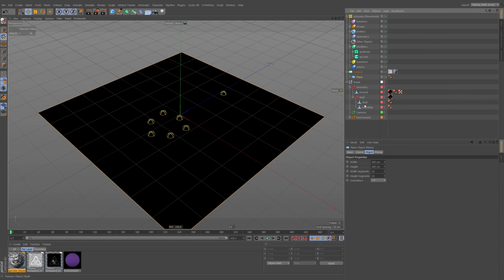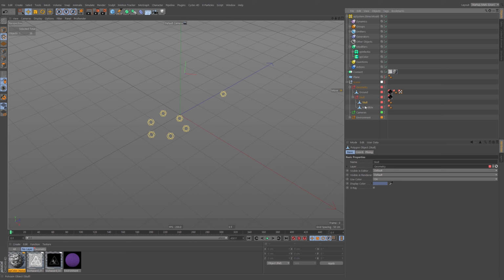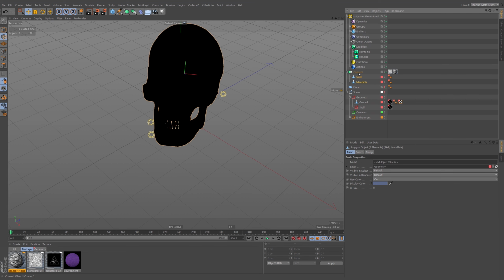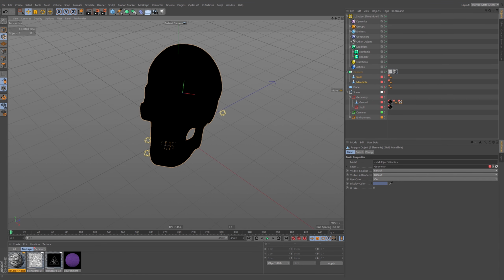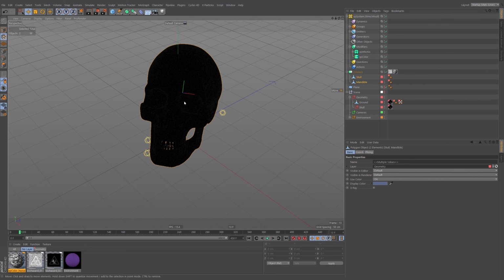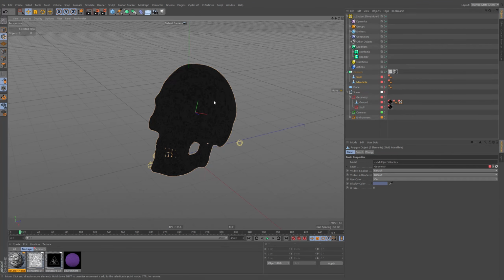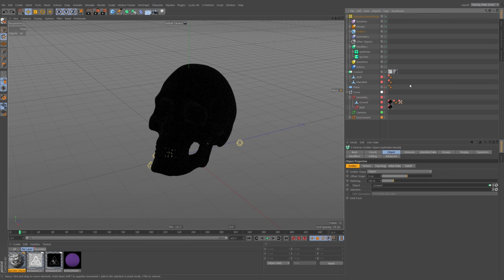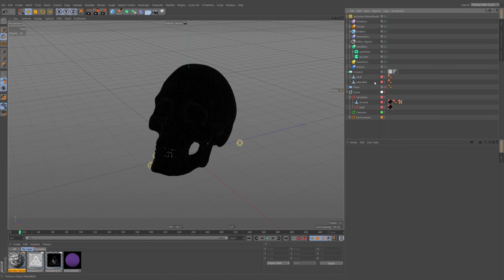Let's grab our skull and mandible. I just wanted to demonstrate two separate objects. If I hide this here, throw these in together. Now, if I press play, I don't think anything's going to happen because, for starters, these materials don't have UVs on them. Also, these objects don't even have a UV on them. So you might discover this kind of problem when you bring in scan geometry and things like that. Sometimes they won't have any UVW at all.